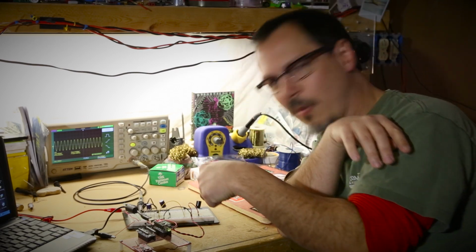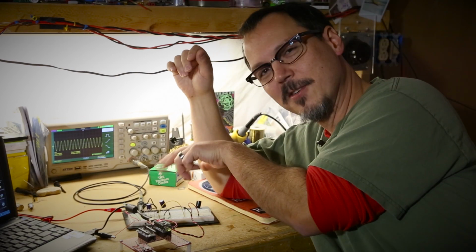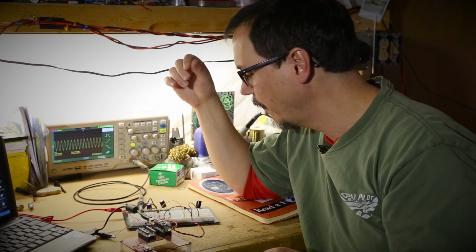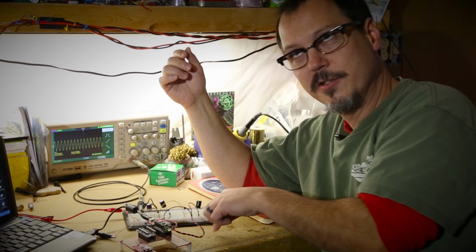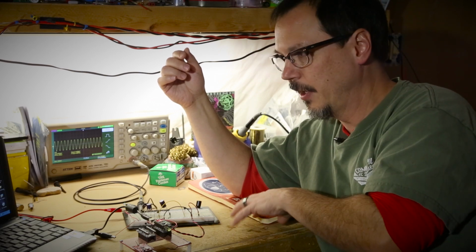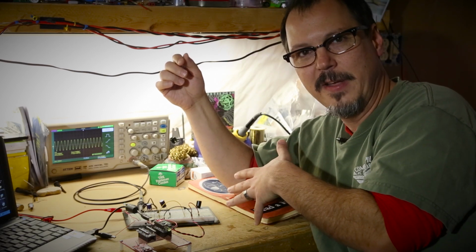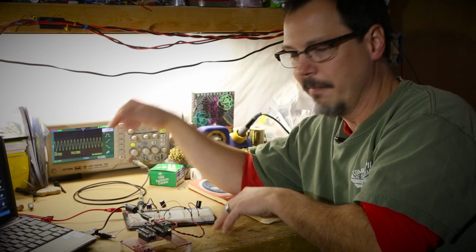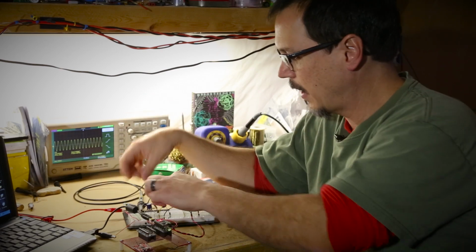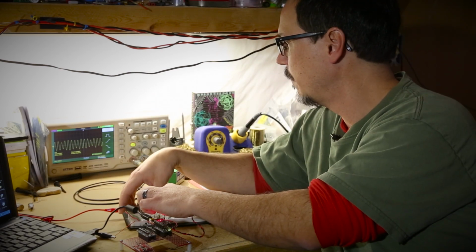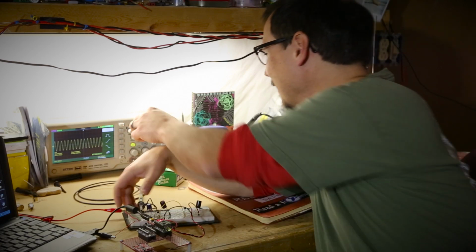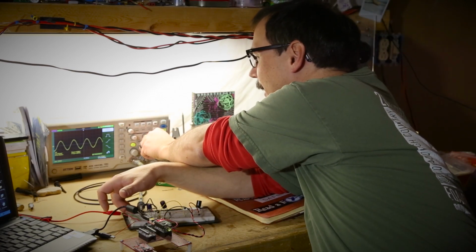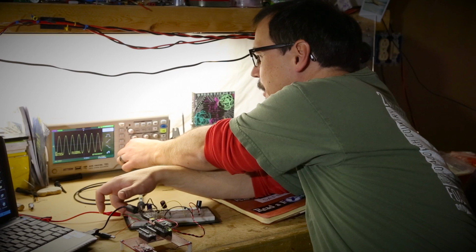stuck in a breadboard. I hate breadboards. You can poke your fingers in here and do funny things. You can mess with the waveform, right? As I was talking about before, from collector to base is effectively 180 degrees worth of phase shift. So if you couple a signal from front to back, you get negative feedback, and you might get some really wiggy stuff. Now, I don't know if you can see that waveform, and granted, a lot of it is probably noise, right?